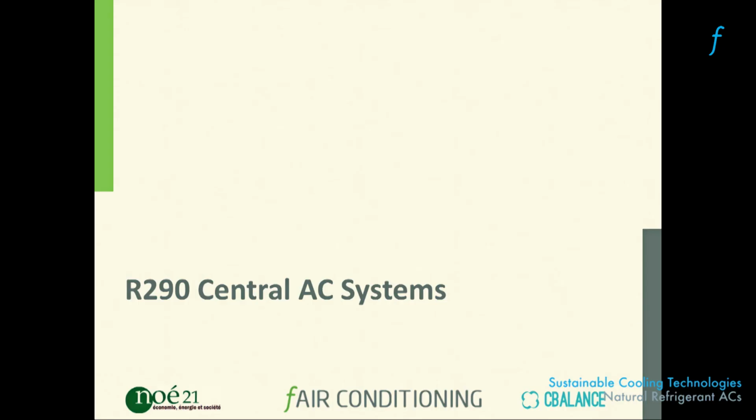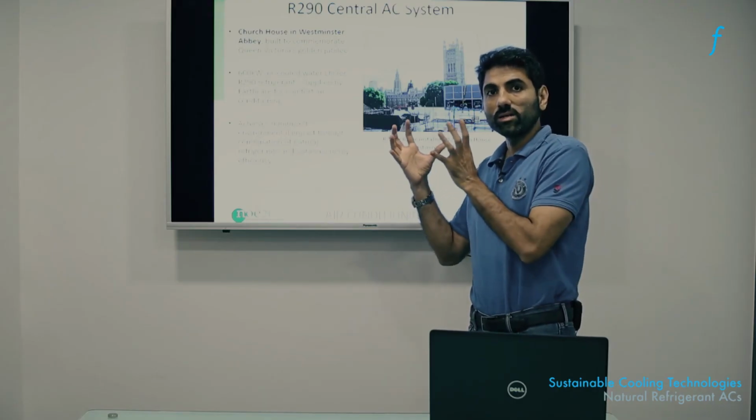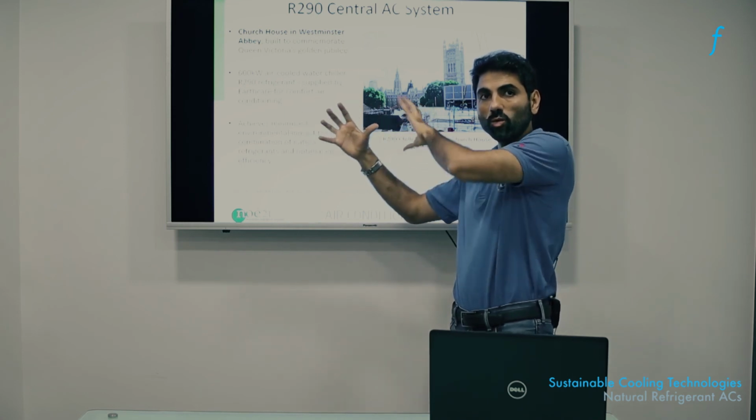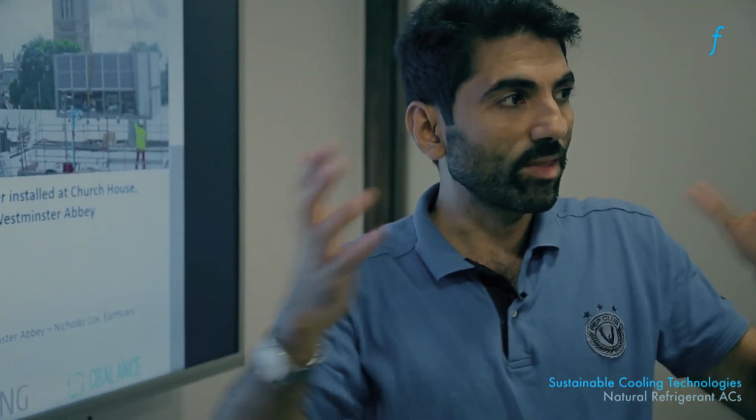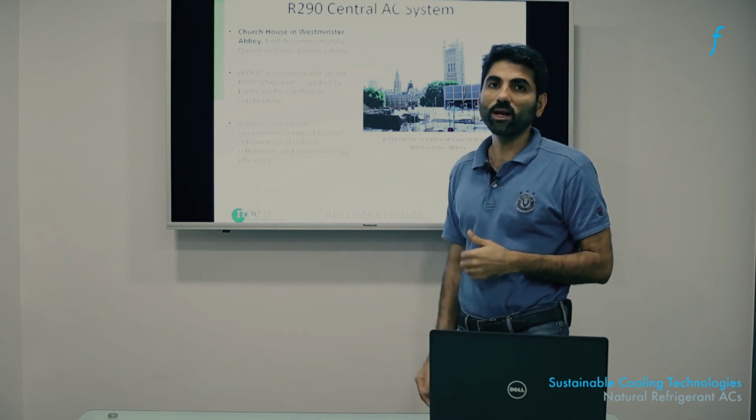The way these systems are able to achieve this is by having a part of the unit outside the building, which is how chillers operate. So chillers are systems which have a cooling system which cools a circuit of water, and it is the water that is circulated through the entire building. Therefore, the safety rules can be different because there are no humans in the part where the refrigerant is enclosed. It's only tubes of water, and the safety considerations for water are very different from those of human occupation. So these systems are able to have 2 cooling loops. One is the refrigerant cooling the water, and then the cooled water going into the building. And in this way they can have systems as large as 200-300 tons.